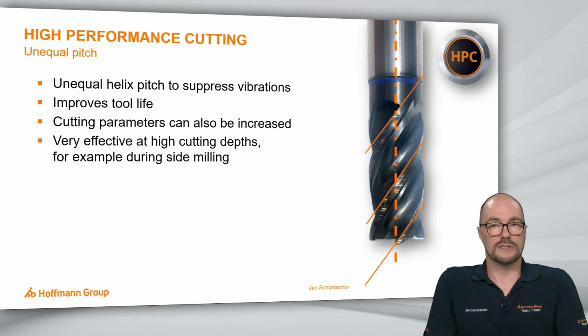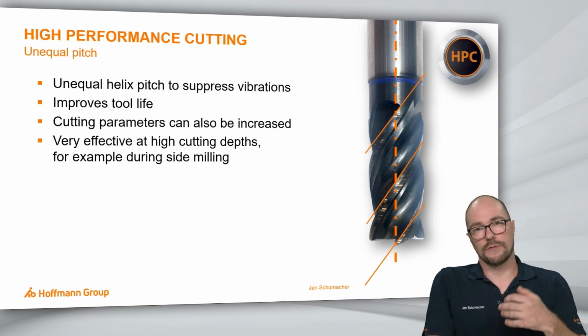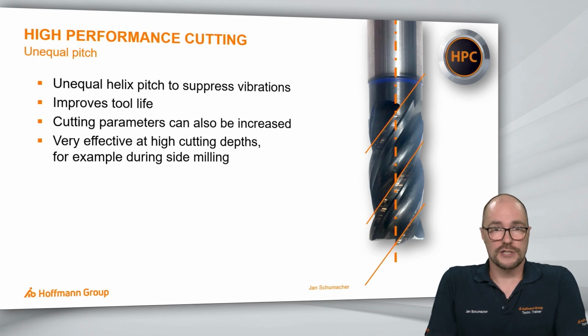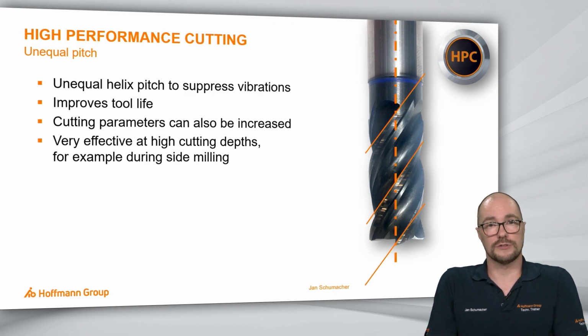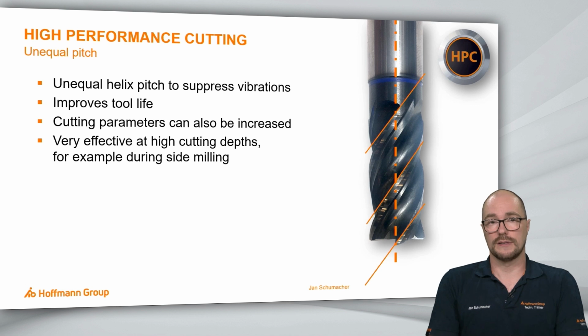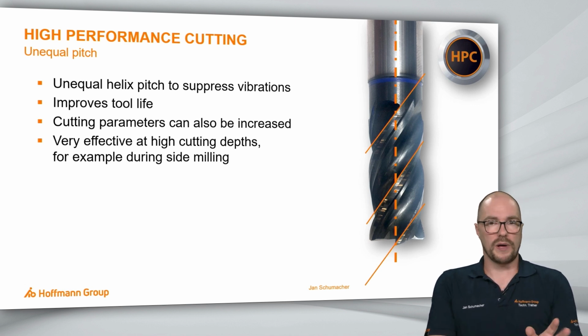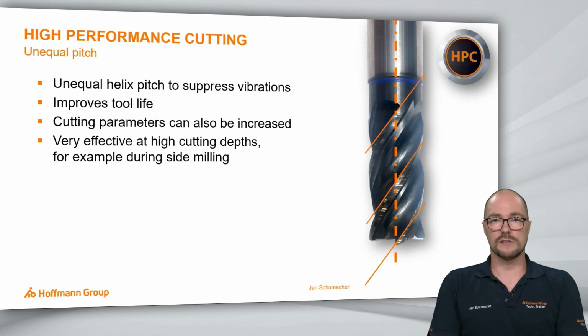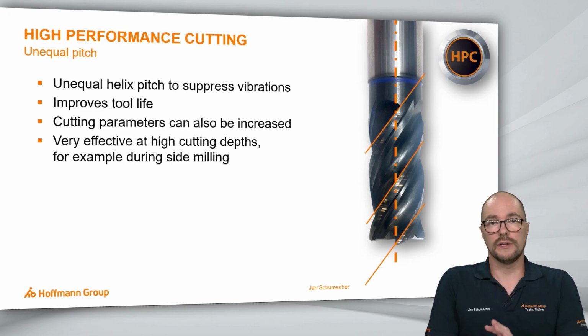This is also something that can help us a lot. It furthermore suppresses vibrations to increase the tool life, of course. But this feature is particularly effective at high cutting depth, for example, during side milling. You will benefit a little less in full slots, but here it can play its cards during side milling.